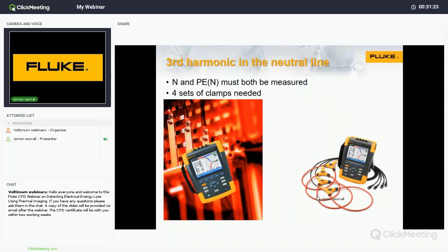And this brings us back to an important thing because there's lots of choice for power quality analyzers that are out on the market. If you are going for one, make sure you go for a unit that measures the neutral current and doesn't calculate it. There are lots of low-cost analyzers in the market that will calculate the neutral current from what you've got present.